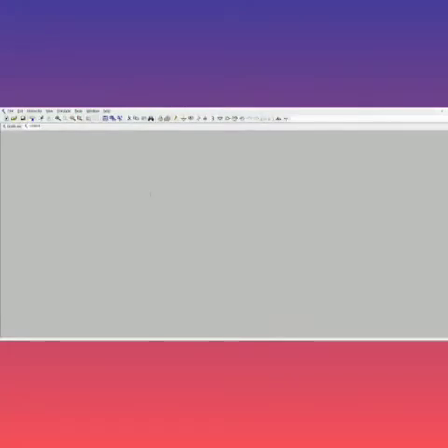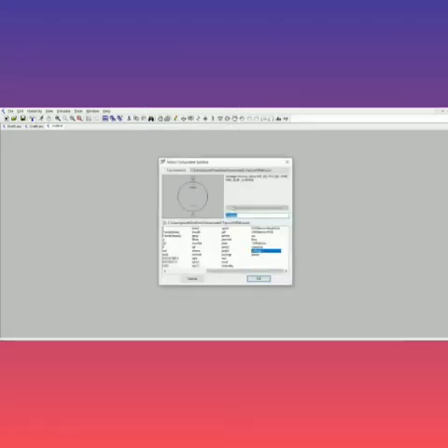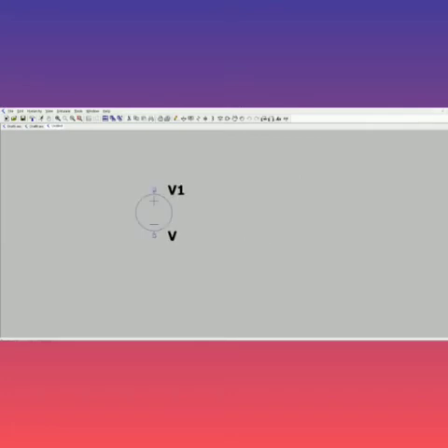Hi everyone. For today's session, we will see how to design the circuit for clamper, positive clamper and negative clamper using LTSpice. So the first step is go for File, New Schematic, then choose the components which you want to design the circuit. So go to the component, type voltage. So you'll get the voltage source, give OK. So right click, it goes off.